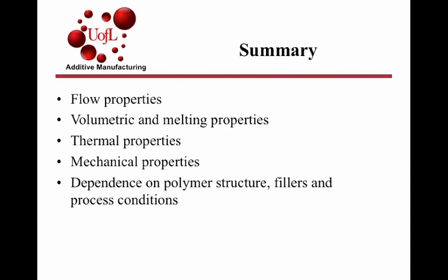So that's the holy grail. Not to just develop new materials, but know whether it will be useful beforehand and know whether it can be created into dimensionally precise shapes beforehand, rather than going through a whole lot of experimentation, which is expensive and time consuming. So the design rules for materials, for filled polymers, were introduced because they come in very handy to be able to design for function and processability by changing material composition.